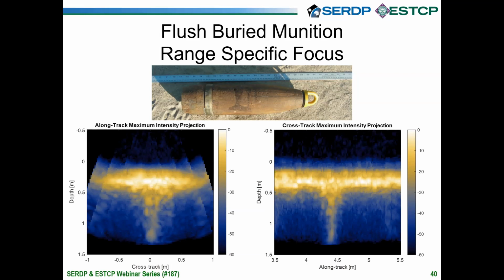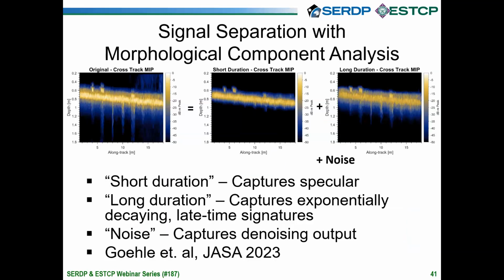The real goal here, and the thing that we're quite excited about, is in extending this work and applying machine learning to see if this improved contrast of this return allows us to improve our ability to classify this object. One thing that is apparently clear is that if we're attempting to characterize the spectral content of this later return, we can now take a much tighter spatial window around that. We can reject more seabed reverberation, and we should be able to realize a higher signal to reverberation ratio in that region and get a cleaner look at those spectral clues.